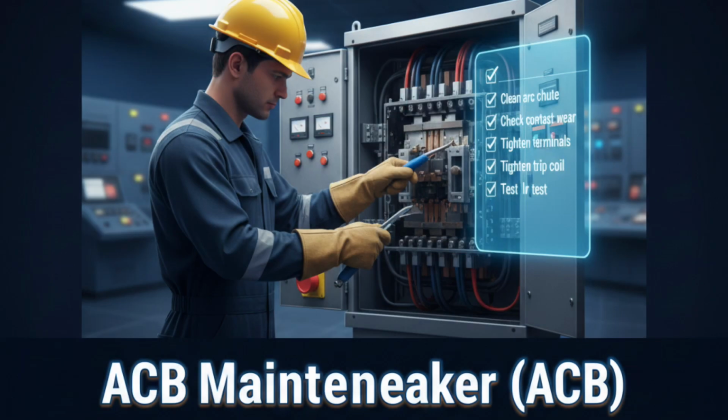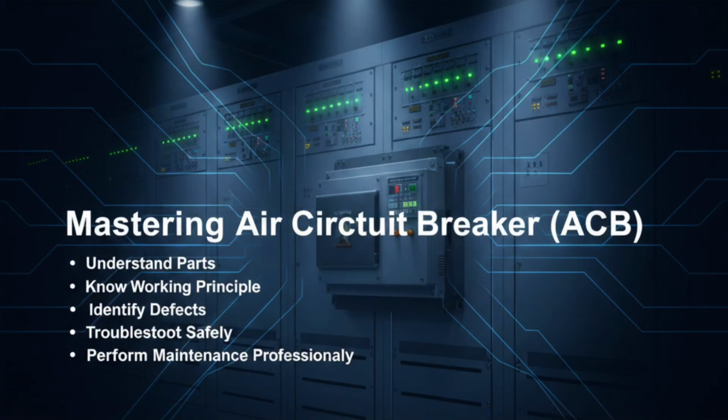ACB maintenance and inspection. Maintenance should follow the PMS schedule. Visual inspection: check dust, cracks, loose parts. Contact inspection: check wear and pitting. Arc chute cleaning: remove carbon deposits. Terminal tightening: prevent overheating. UVR testing: ensure proper tripping on voltage failure. Trip coil testing: verify electrical trip function. Insulation resistance test: ensure proper insulation. Functional trip test: confirm real operation. Maintenance increases the life of the breaker and ensures safety during a fault. Never skip testing procedures.